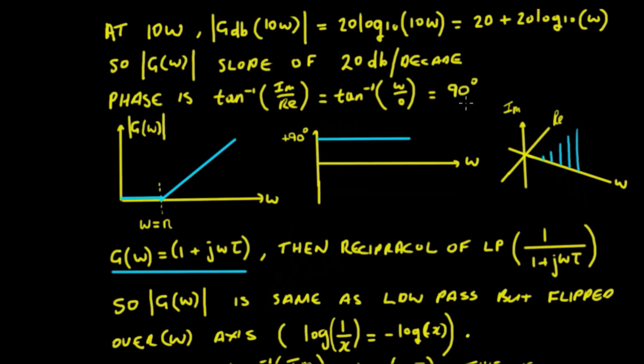Okay, and the value of the phase would be 90 degrees, and again, if we were to put that on a three-dimensional plot, we would have a purely real value, a purely complex value at an angle of 90 degrees, and it would just be getting up at 20 dBs per decade. Okay, so it'd just be a line running up here which lies in the imaginary plane.